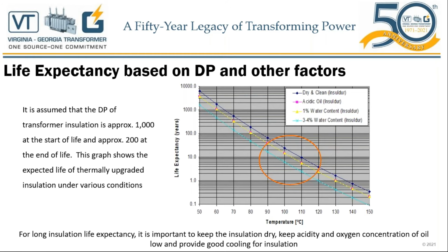The change is a lot. Of course, we run our transformers at 110 degrees, we run our transformers at 90 degrees. So if you study this graph more in detail, you can understand, as I did years ago, the importance of not only the temperature, but the effects of other factors aging our transformers' insulation. And if the insulation ages, transformers' life expectancy reduces against mechanical stresses and dielectric stresses, as we saw in the picture before.